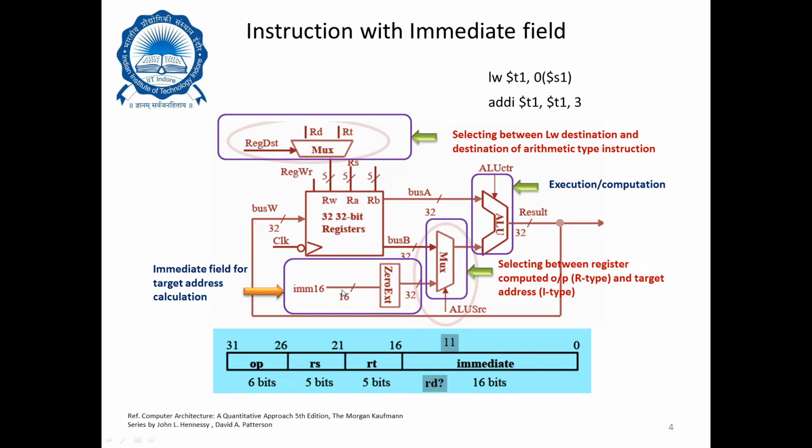But if you recall, in the last lecture I said that a 16-bit value cannot be fed directly into the mux, because we need to pass it through a sign extension unit or zero extender unit that adds zero values as padding to make it look like a 32-bit value, and that 32-bit information gets into the mux. So this 32-bit information is one of the inputs of the mux, and the other 32-bit information is the output of the register file that gets into the multiplexer.